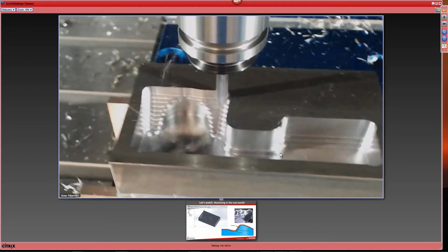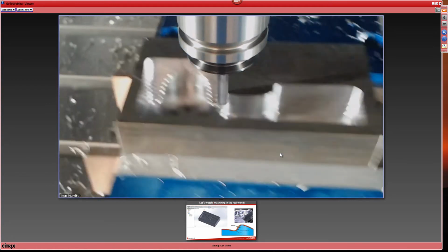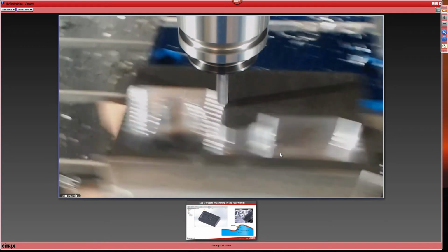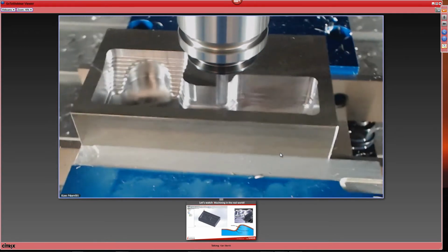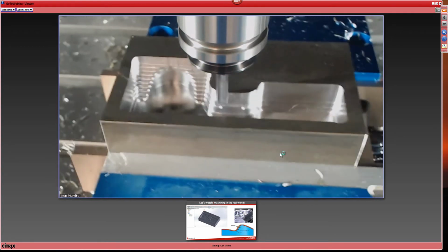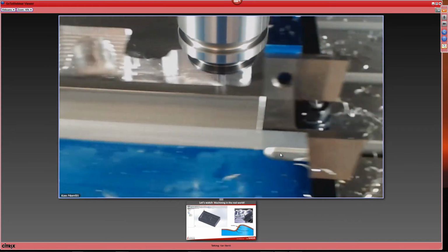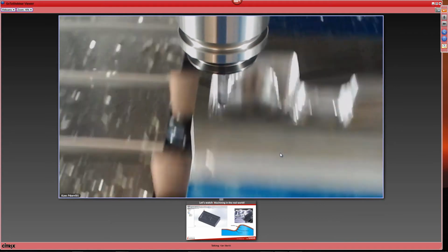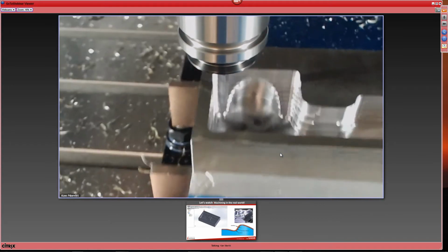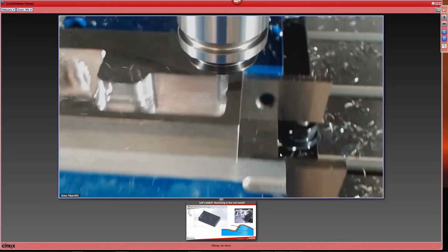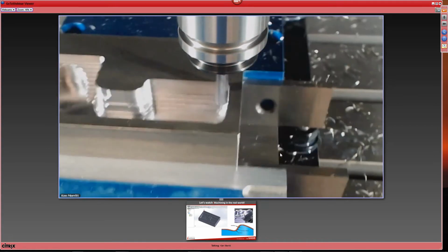Now, as we get deeper and deeper into this, you're going to see that regardless of the angle of the surface, the scallop height of the staircases is going to be the same. The algorithm automatically looks at what we call the inclination angle of the surface and computes the Z-step height to make sure that the maximum staircase offset is controlled and is uniform throughout the part.